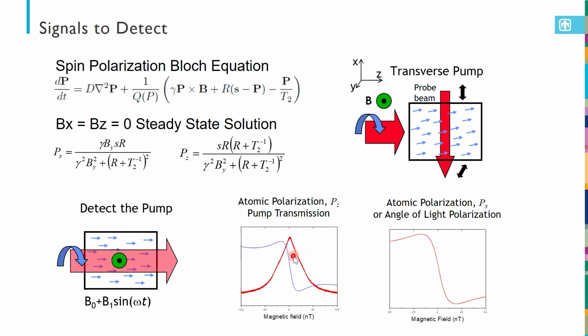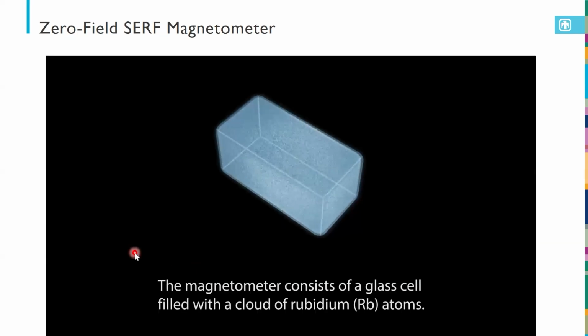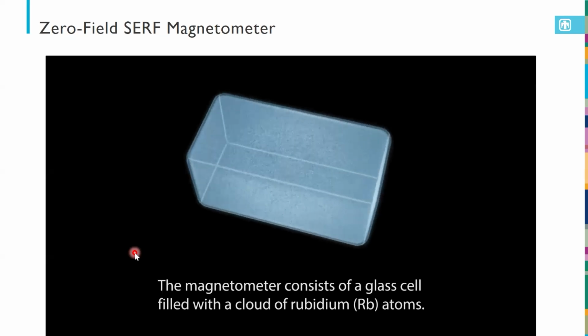And then we go in and do lock-in demodulation. We take the photodiode output signal, send it into a lock-in amplifier, demodulate the signal, low pass filter it, and then we get, again, a linear slope. One way to think about demodulation is essentially you're taking the derivative of this signal here. And so once again, we have this nice linear slope that we can use to do a sensitive measurement of the magnetic field. This is a video from NIST that shows this concept, the single beam magnetometer.